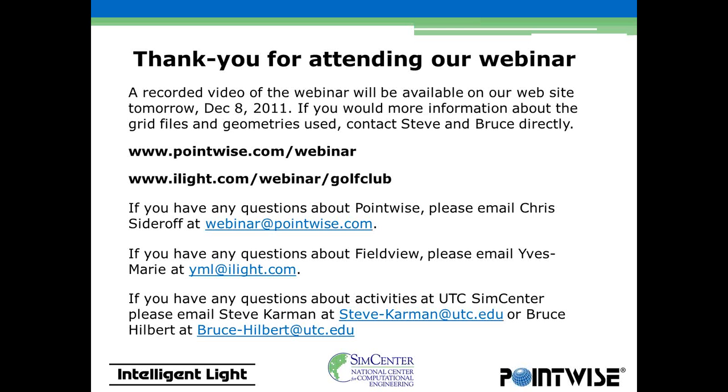No, there's not a direct coupling, but part of what Steve and Bruce were showing is that, through the flexibility in the formats that Pointwise supports, it's very easy to couple. They're seemingly two very distinct meshing approaches, but because voxel mesh requires a triangulated surface mesh to begin with, he's able to do that fairly easily in Pointwise as well. The application he was showing was fairly simple, just a sphere, but you can imagine a much more complicated case where you need some CAD tools and extra facilities to create a more complex triangulated surface mesh that he can provide to voxel mesh.